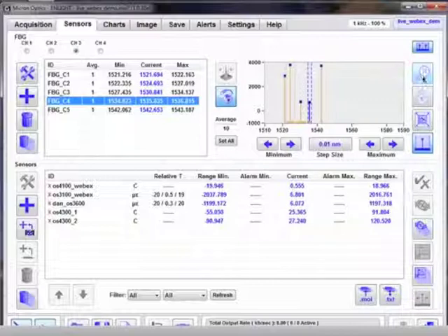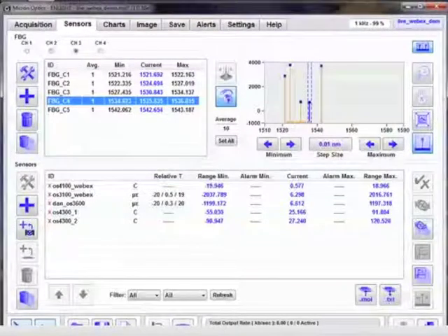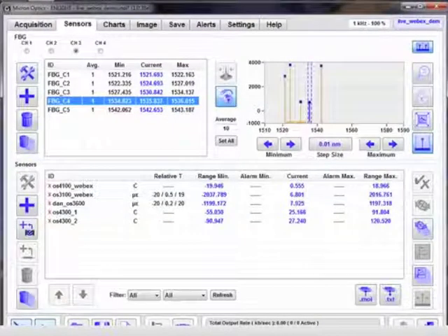So now, say you set up your system, you zero everything, 3 months later you add a strain gauge, you can use the existing temperature compensation FBG and you can zero the new strain gauges without affecting the previous gauges using that compensation element. And that's something we will demonstrate here by adding an additional sensor.